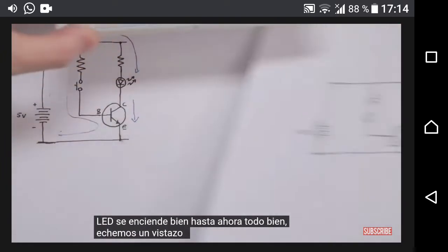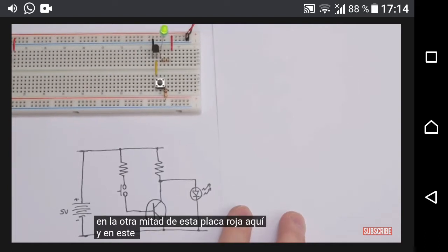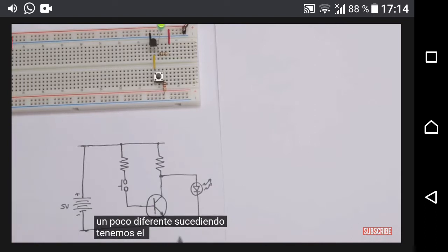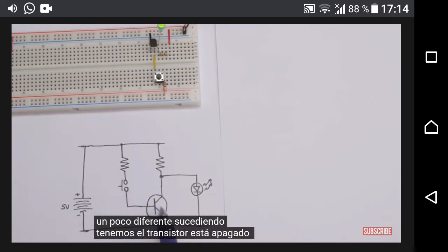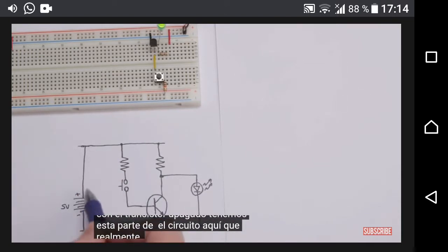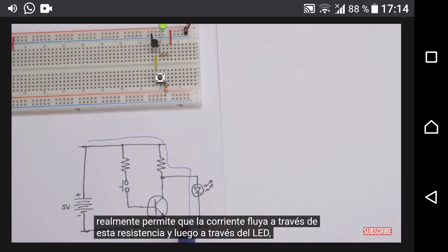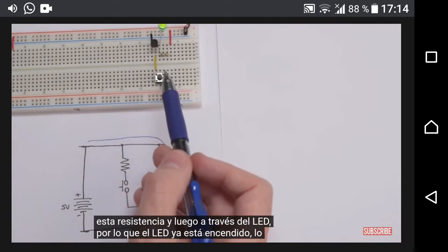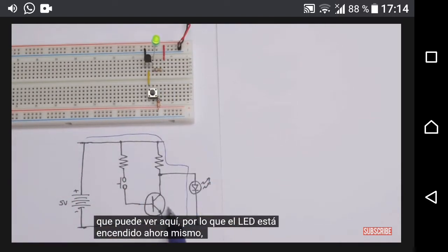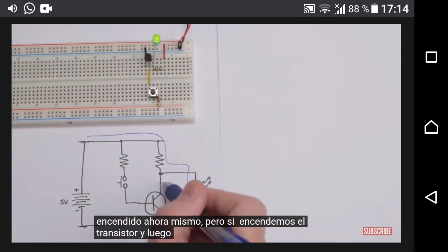Let's take a look at another circuit, which is on the other half of this breadboard here. In this circuit, we've got something a little bit different going on. The transistor is off, but with the transistor being off, we have this part of the circuit here, which actually allows current to flow through this resistor and then through the LED. So the LED is actually already on, which you can see right here.